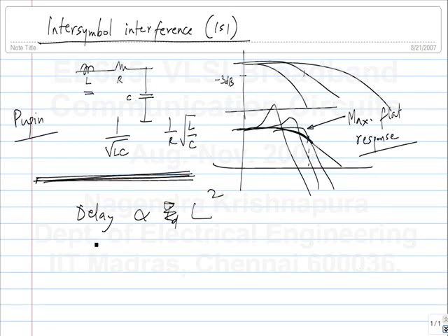But what was puzzling was, if you look at delay per unit length, for every meter of wire, that itself is dependent on L. So it appeared as though the delay that is offered by every length of the cable depends on the total length. But how does the cable know that the rest of the cable is connected to it? That's a little weird, right? But it comes out of the diffusion equation, and this is the right thing.